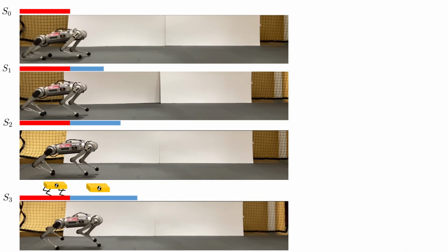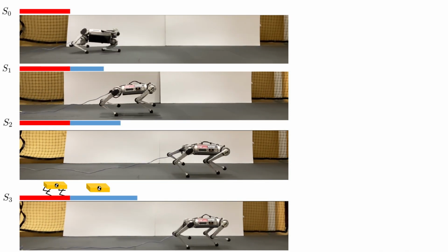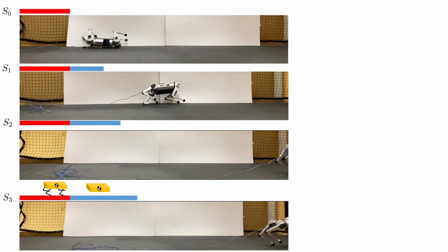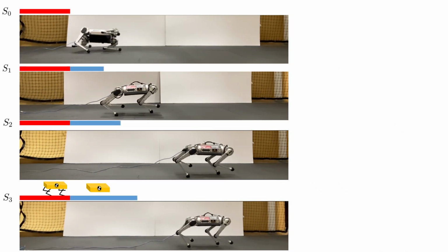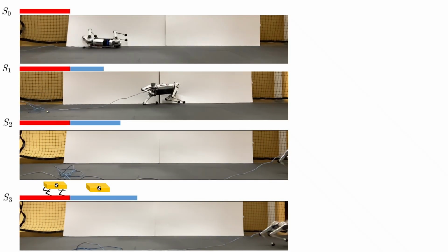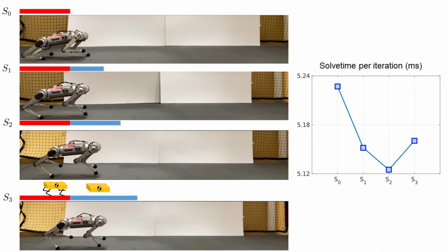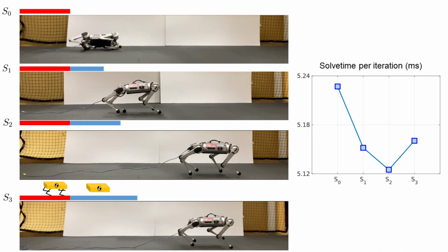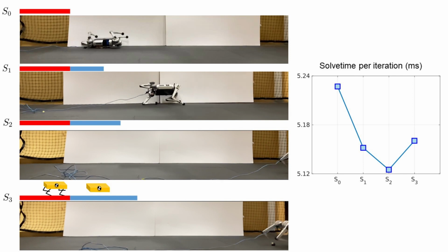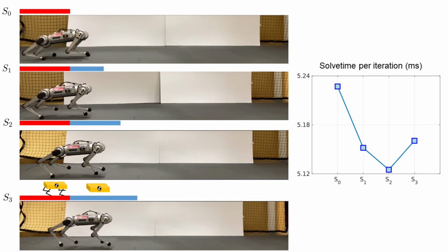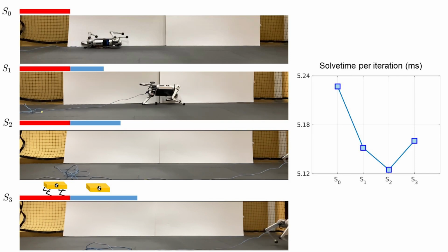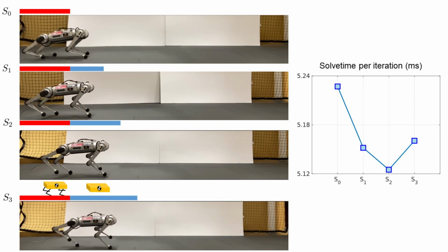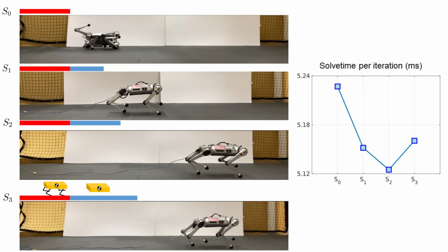With a short SRB plan, the controller attained bad tracking performance. As a result, the robot gradually drifted and fell. The tracking performance is significantly improved as longer SRB plans are employed. Moreover, growing the SRB plan appropriately does not necessarily increase the average solve time per iteration. This is because with the longer prediction horizon, the local feedback policy may have a larger region of attraction, resulting in more aggressive step sizes for the line search.